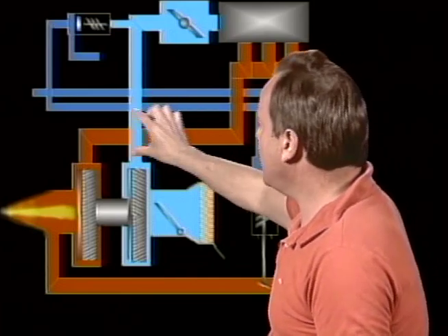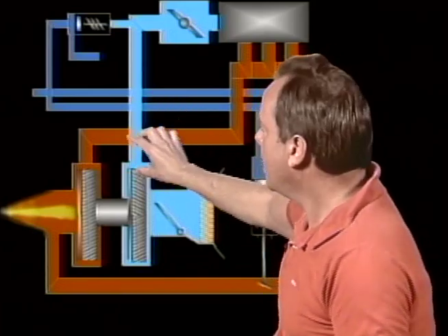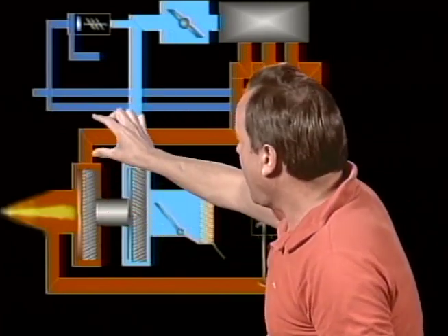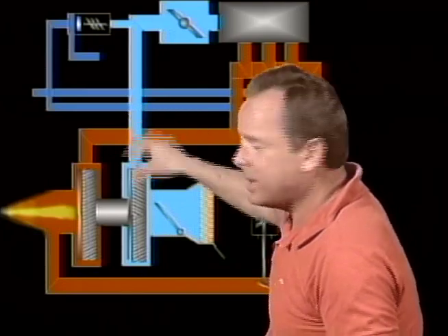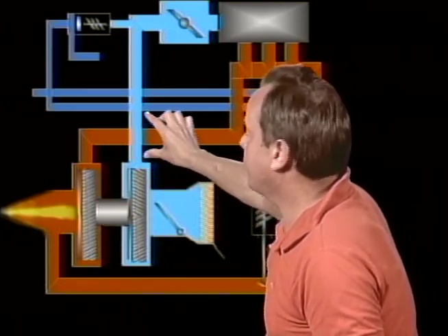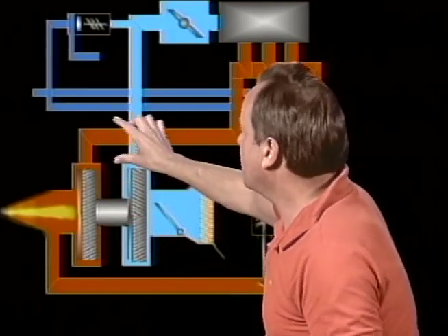And now you have a heat exchanger called an intercooler, and you take air from the slipstream of the aircraft that's cold because it's cold outside at high altitudes, and run it past, without mixing them, this hot air that's just been compressed from the turbocharger or supercharger and cool it down. That's called an intercooler. What would be the purpose of that? And the answer is to cool the air entering the carburetor from a supercharger.